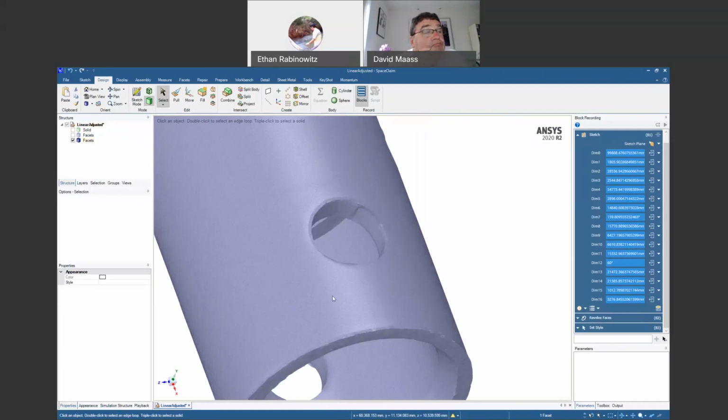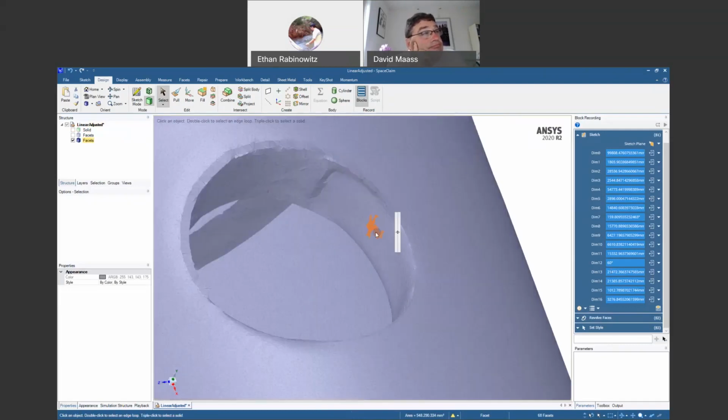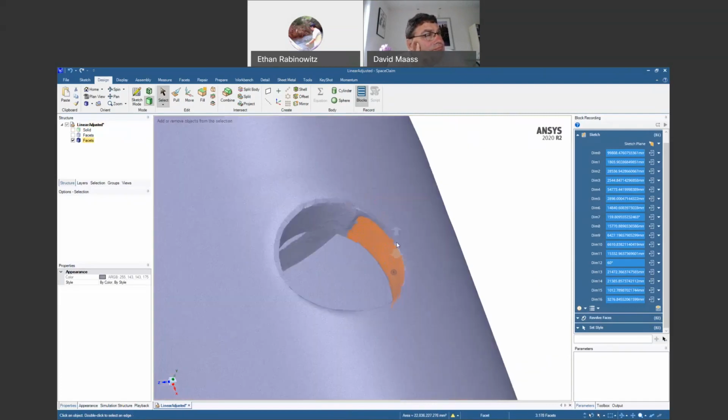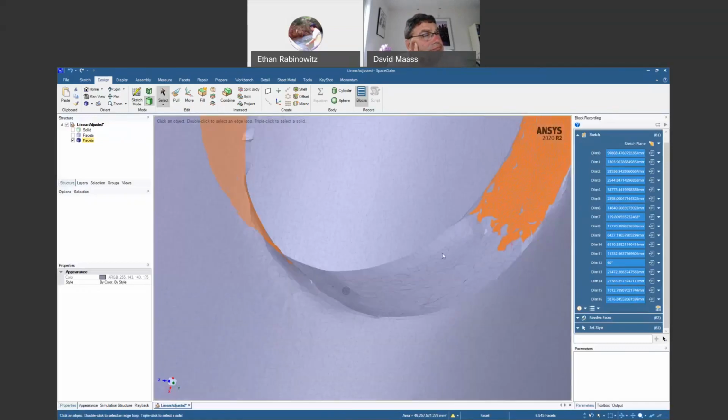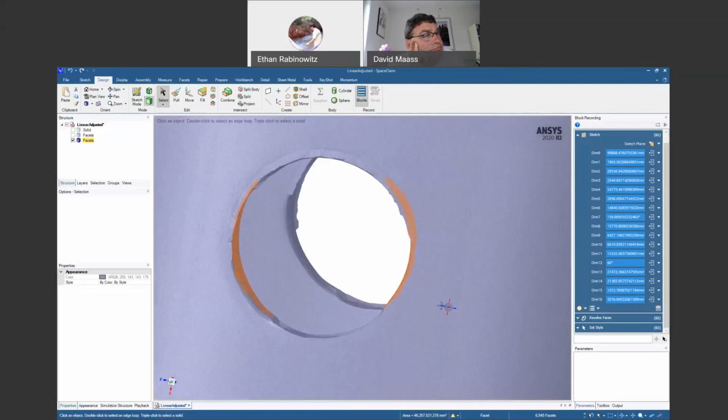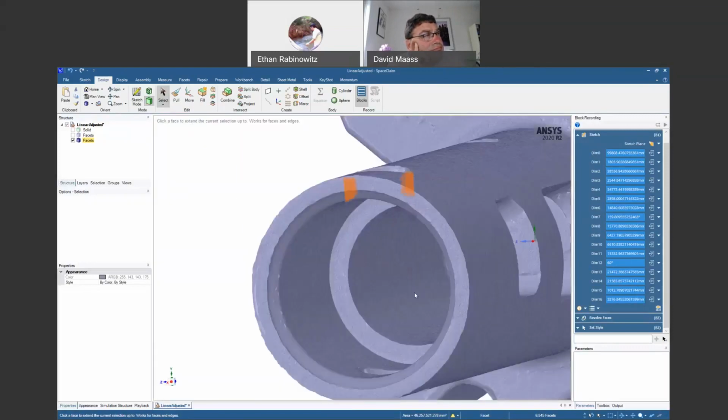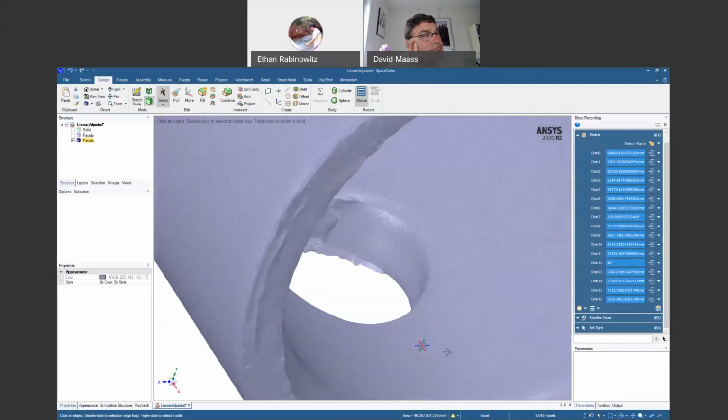So this method highlights sketching. Here, I'm going to double click and that grabs some facets. Then I can use this slider and grab some more facets. Now, if I drag it up too high, it'll select too many because it's changing the angle between the facets that it'll select. So I may want to grab some there, hold Control, double click over here, slide that up a little bit. Maybe I decide that I don't want to use this data here to fit with, and so maybe just those two areas look good there, and then maybe something similar here.